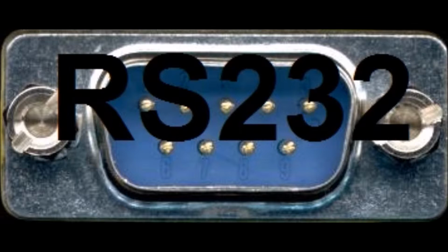Electronic data communications between elements will generally fall into two broad categories: single-ended, like the RS232, or differential. RS232 was introduced in 1962, and despite rumors of its early downfall, has remained widely used throughout the industry. Independent channels are established for two-way communications, otherwise known as full duplex. RS232 signals are represented by voltage levels with respect to a system common.